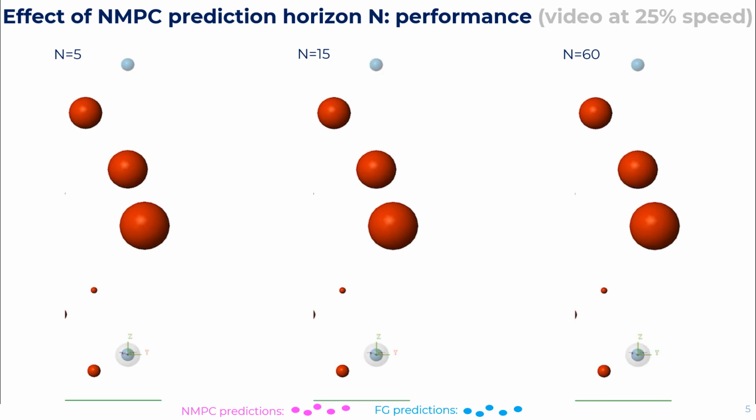For the longest horizon of 60 steps, the quadrotor is extremely agile, showing tilt angles exceeding 90 degrees. It passes very close to the obstacles and reaches the target first. For the intermediate and short horizons of 15 and 5 steps respectively, the quadrotor shows less aggressive performance. This is because there is a larger part of the trajectory prediction dominated by the feasibility governor, which will reduce the dynamic safety margin and as such the velocity of the auxiliary reference, when the prediction of the terminal closed-loop dynamics is close to obstacles or other constraints.